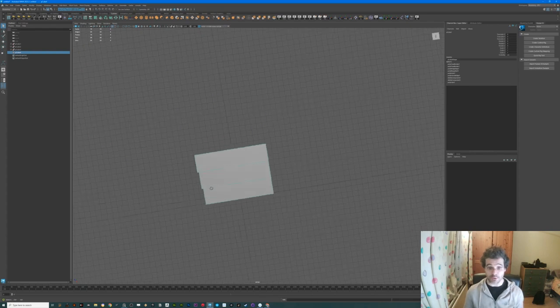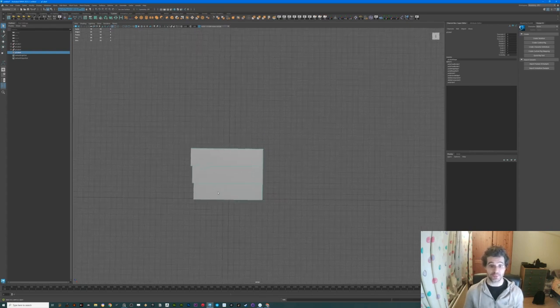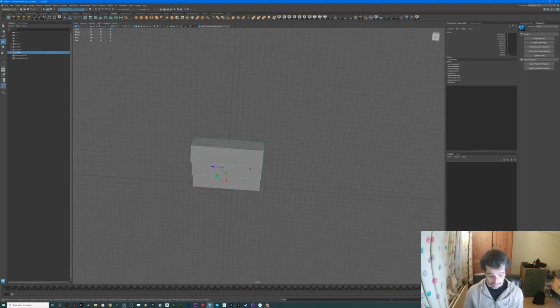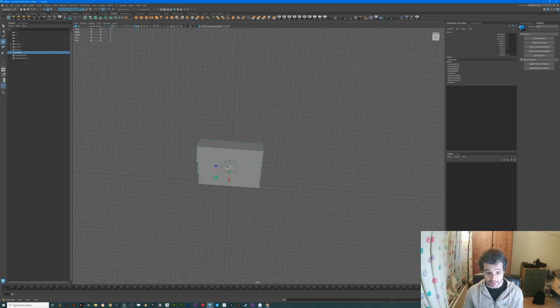as a modular set piece. So I want this to be able to do convex and concave shapes. So I'm going to duplicate this. To duplicate, I select our shape. I'm going to press D to reposition the pivot. By pressing D, I get the pivot to reset it. I'm going to press and hold V, and by holding the V key and middle mouse dragging this yellow circle, I'm going to snap it to the corner.